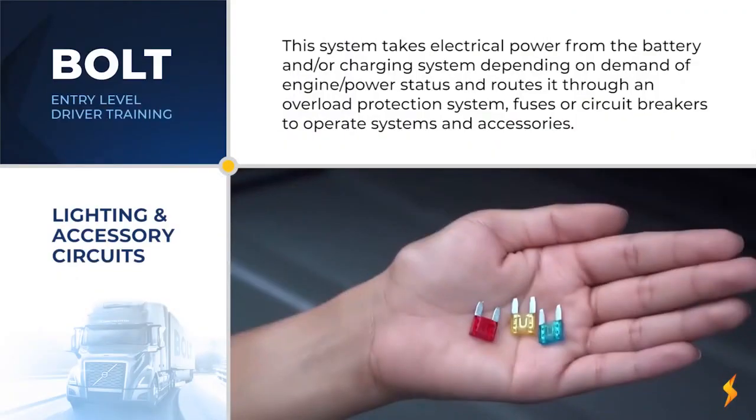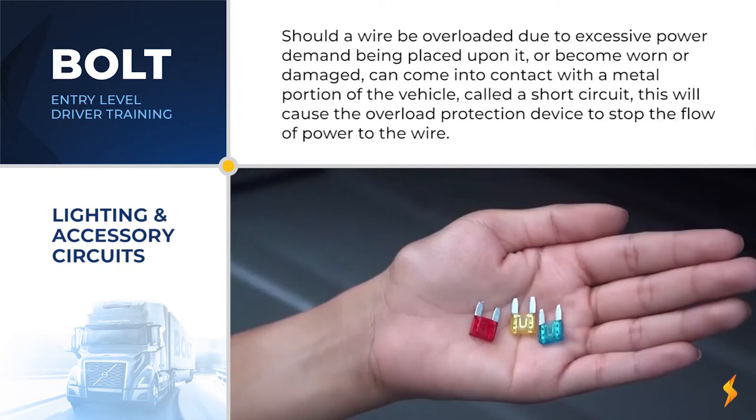This system takes electrical power from the battery and/or charging system, depending on demand and engine power status, and routes it through an overload protection system, fuses or circuit breakers, to operate electric systems and accessories. Should a wire be overloaded due to an excessive power demand being placed upon it, or become worn or damaged and come into contact with a metal portion of the vehicle, called a short or short circuit, this will cause the overload protection device to stop the flow of power to the wire.